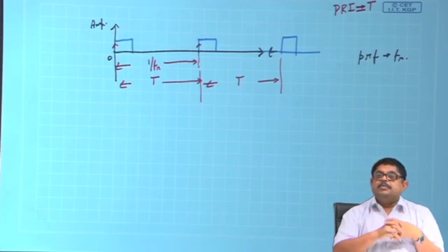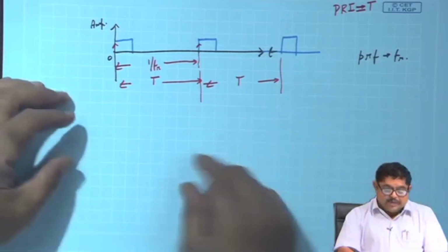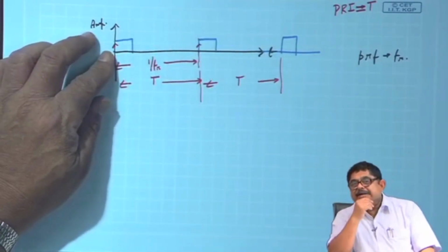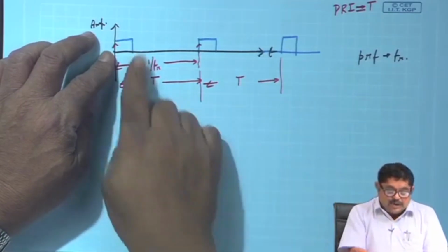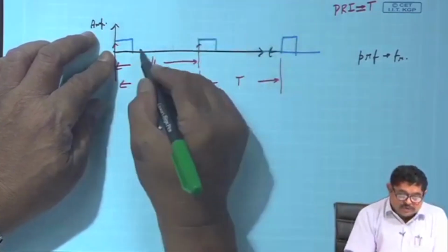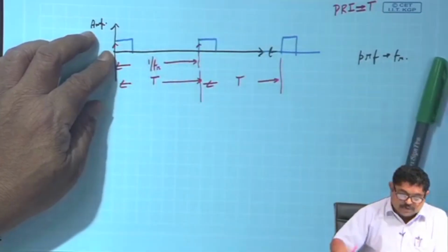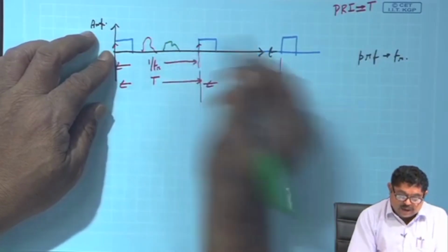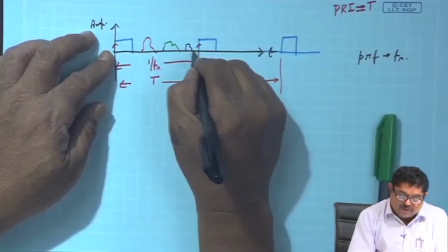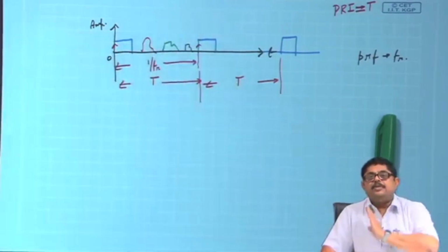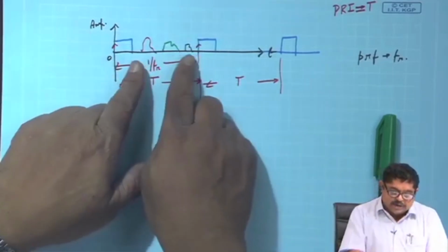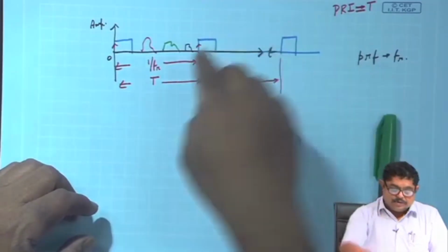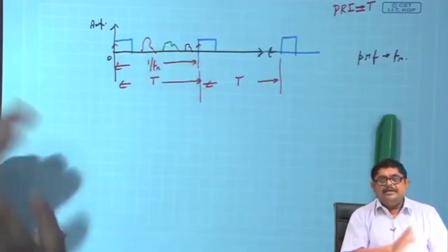Okay. Now, if my entire range measurement is to be unambiguous, what I expect is that all the echoes from the various targets at various ranges arrive in order. Suppose the first echo arrives here, the second echo is here, the third echo is here, then I do not have any problem. That means I understand that the black one is at the far maximum distance, or its range is maximum. So, if I measure, then I will get it.